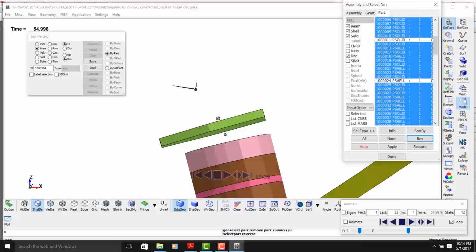And this height of 0.7 inches is the same for all Hybrid III adult dummies: the 5th percentile, the 50th percentile, and the 95th percentile. This lever arm is the same, 0.7 inches, 17.78 millimeters. So whatever moment comes out at the load cell has to be corrected by a certain amount. And what is that amount?